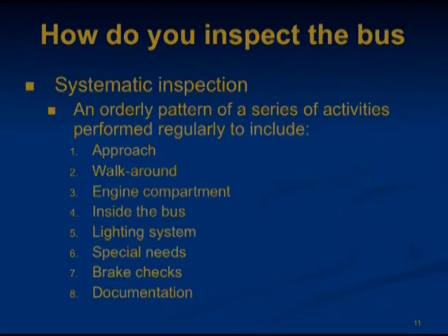Okay, so how do you inspect the bus? You will use a systematic approach to include the approach of the bus, the walk-around, engine compartment, inside the bus, lighting systems, special needs items such as lifts, car seats, brake checks, and of course documentation is a part of that pre-trip. The driver is not expected to be a mechanic, but by using a prepared checklist of items to check, the driver can determine the vehicle's readiness for use. Follow your system's set pattern of procedure used to maintain consistency.